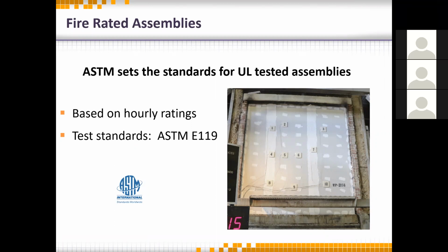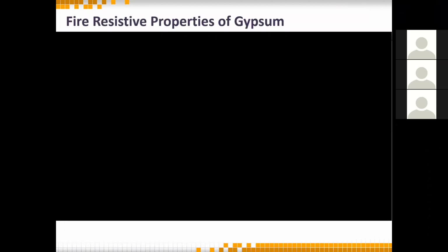Those are thermocouples that have been strategically placed according to the ASTM test to measure the temperature of that board as it's being burned, to see if it is burning through the core. There's also a thin top wire going across to measure deflection if this is a structure that has pressure attached to it. So let's go ahead and watch the video, and then we'll talk about some other things right after.